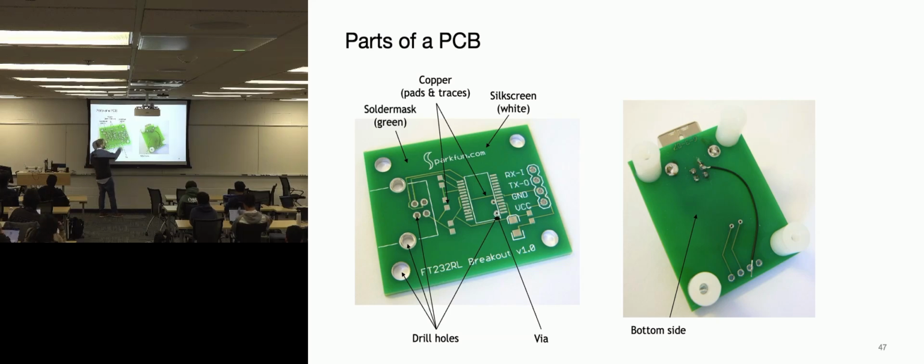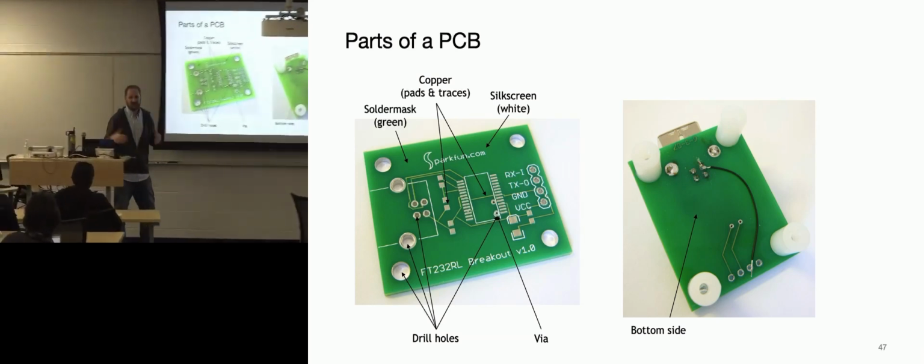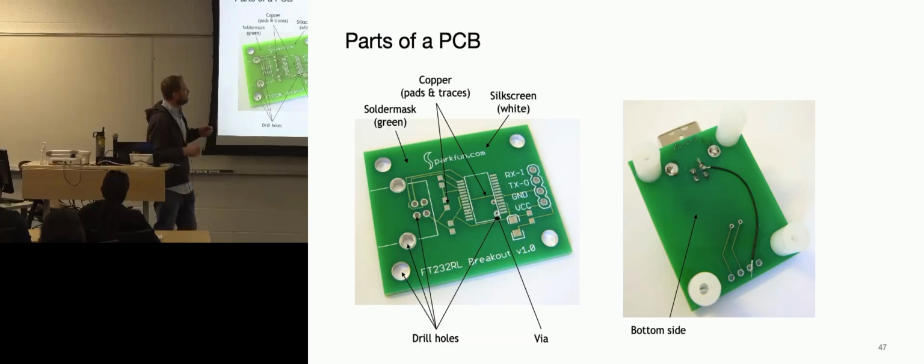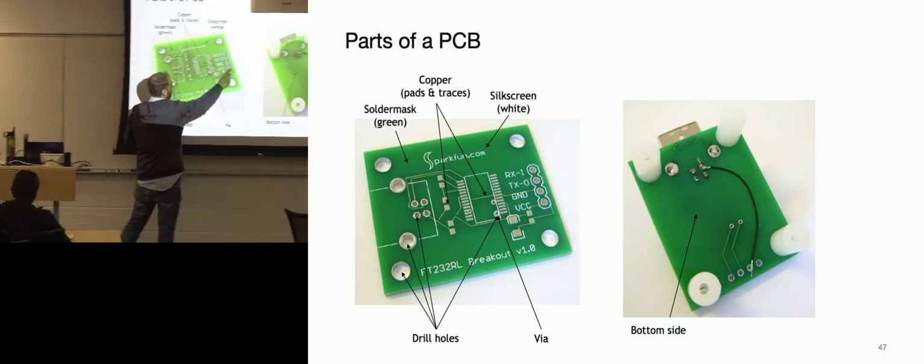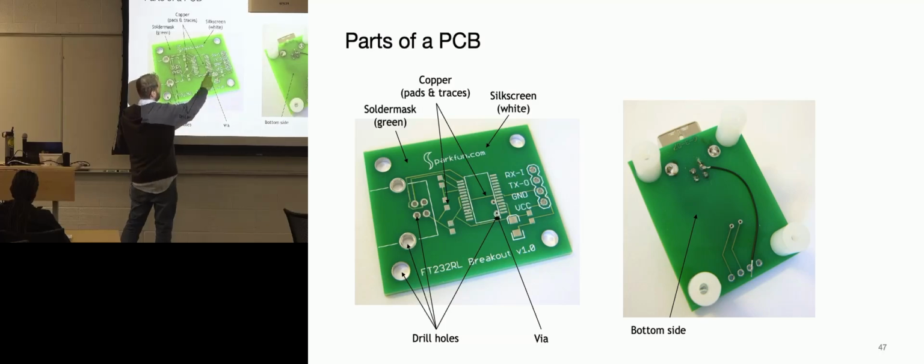The same thing happens here. From the manufacturer's point of view, there's no real difference between a via and a pad with a hole in it for through hole, but your CAD software makes a big difference about it because they have different usages. So: pads, mounting hole, via, and a hole in the pad.